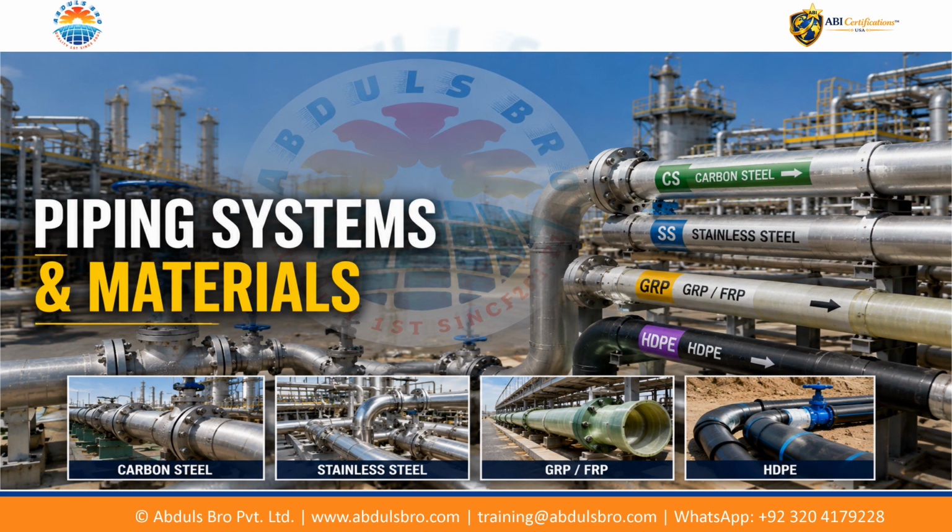Let's have an overview of piping systems and materials. Piping QA/QC requires a clear understanding of the material, service, and design basis of each system. Metallic piping may include carbon steel, stainless steel, and alloy steel, while non-metallic systems include RTR, GRP, and thermoplastic piping such as HDPE. Each system has specific requirements for material selection, joining, flexibility, supports, installation, and testing. Therefore, inspection must always be performed against the applicable piping class, approved specifications, drawings, and qualified construction procedures, rather than applying one inspection approach to every piping system.